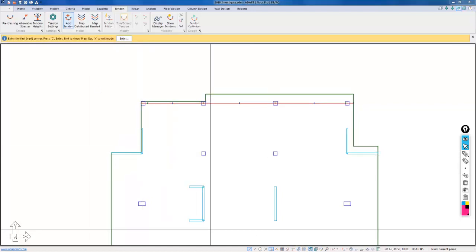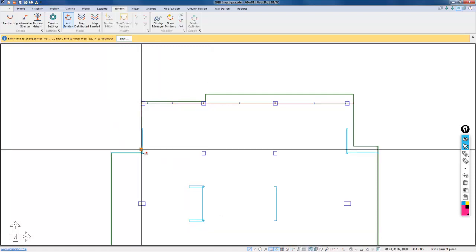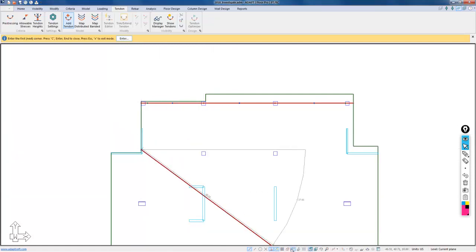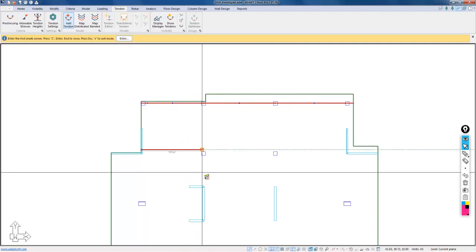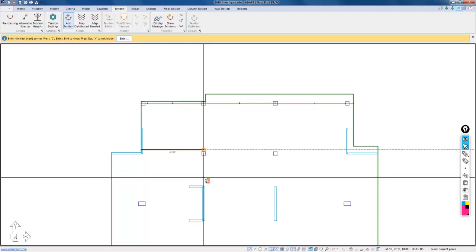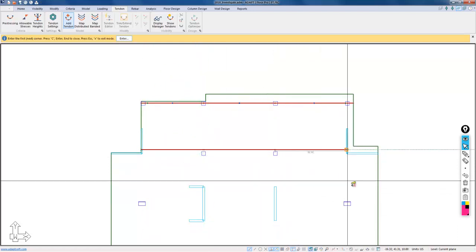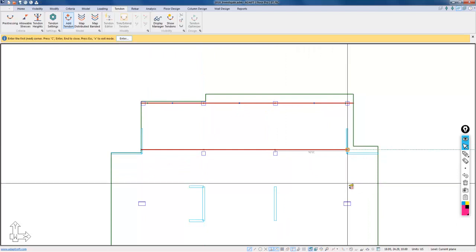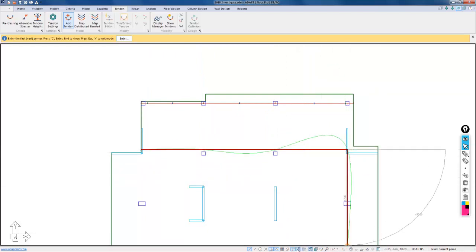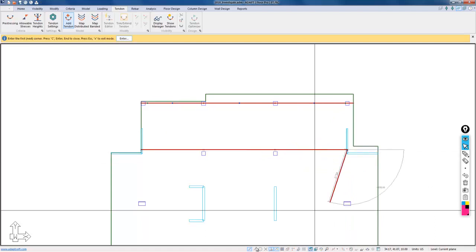We're going to draw one tendon that anchors here, and again I'll use snap orthogonal. I like to use that tool just because it's a little easier to move away the cursor and then see where the tendon's being drawn versus being right on top of it. And then we'll do a cable point there, and then I'll end it again using perpendicular.